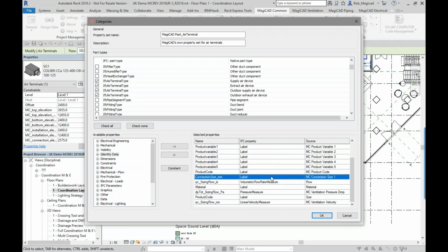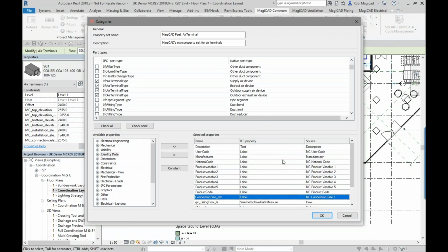So big advantage here, let's say in the UK doing some COBie data drop, instead of putting COBie into a spreadsheet, which can be quite cumbersome, you can still meet BIM level 2 by exporting to IFC with all the COBie data in it, for example, as a format.